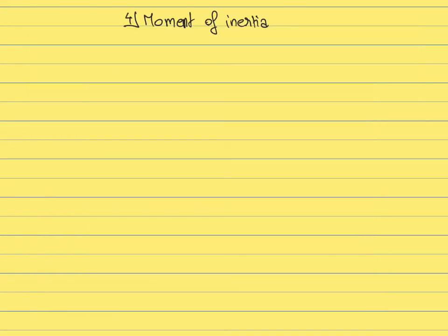So the first thing that we are going to do is to try to understand what the moment of inertia is, to provide its definition, and to get some feeling about what the moment of inertia is actually capturing. So for this, what matters is the shape of the cross-section of the beam. So let's consider a given beam. Let's assume that you have a beam like this, and we are going to assume that the longitudinal axis, the axis that defines the length of the beam, we are going to write it x.